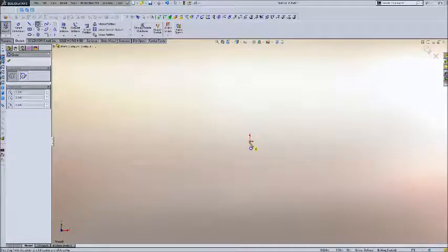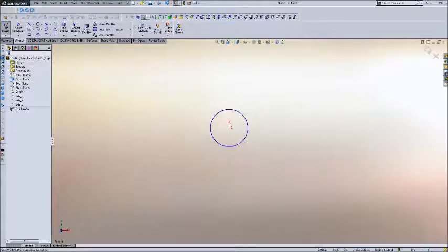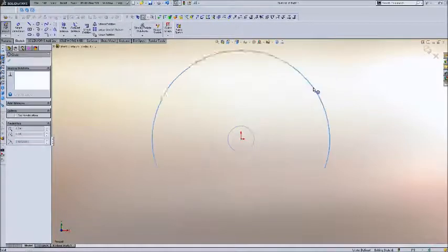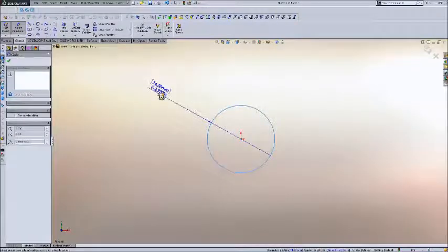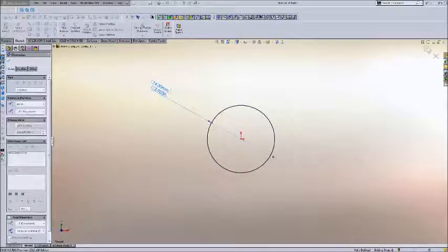So first thing I do is make a circle. I'm going to start at my origin, because that's where you should start most of your sketches in SolidWorks. And of course, this is blue, I can't drag it around, but I can increase the diameter, so it hasn't been defined yet. So I need to define the circle's diameter. The diameter I'm going to define is the outer diameter. I'm going to do that by taking the outer diameter formula, which I'm going to put in the smart dimension. You won't be able to see this. I don't know why Open Broadcast software won't show it. You just see that I have a dimension there, but it doesn't show that I'm actually editing it.